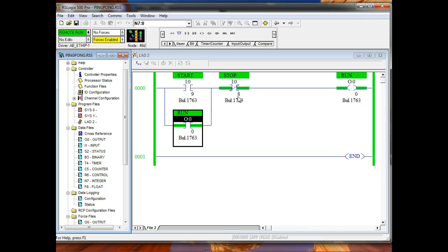So this is my stop button. Right? Yeah, this is my stop button. Stop, start, and I'm going to simulate breaking this wire right here. Now I can't do what? I can't start it. I can't stop it. Right? Y'all understand? Yes or no? Because it's an examine if open. Well, what's the problem? The PLC sees it as what? Open. Right? Y'all understand? So this is what we get back. Right? So this is why when we come in and now I can stop it.